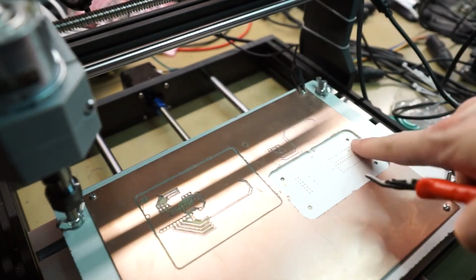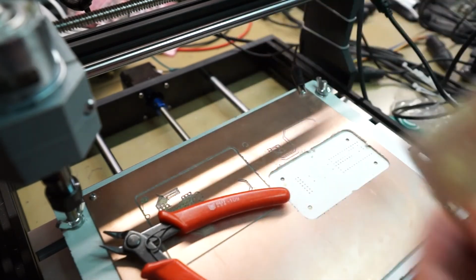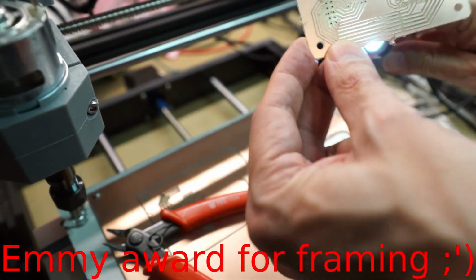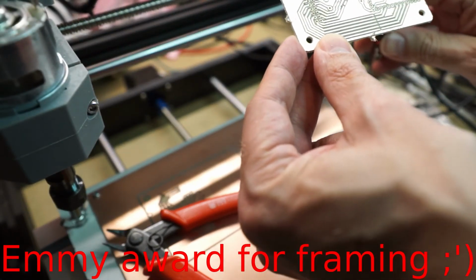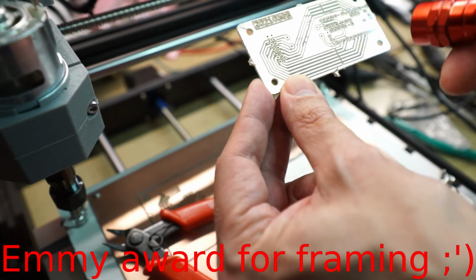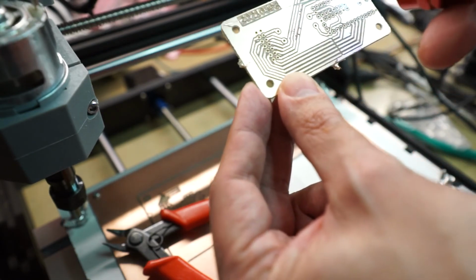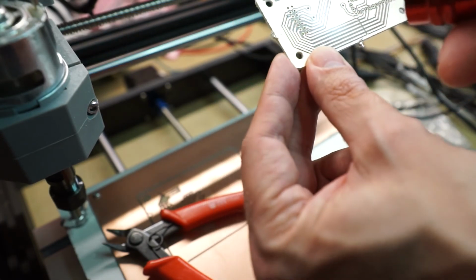So you see that the holes went right through, which is great. We have a circuit board. Well, holes are done. Holes are good. Even though I used a 1mm, which in retrospect was probably a big one, I made the pads 2mm and I lined it out. I'm gonna have a look at this under the microscope, clean it up a little bit. We'll see where we are.